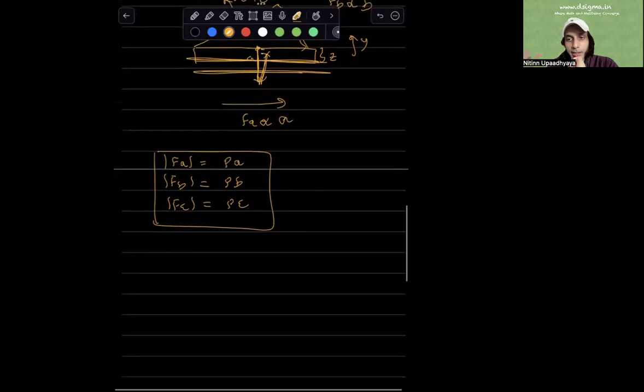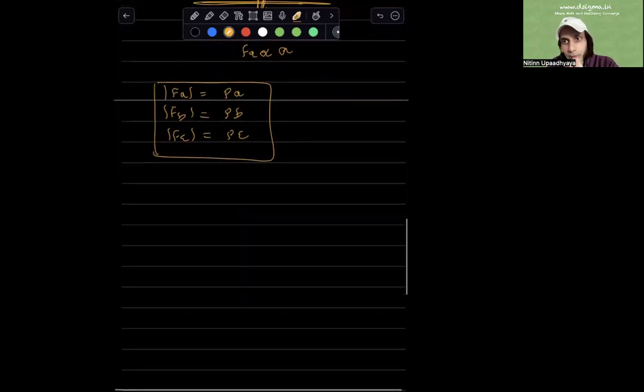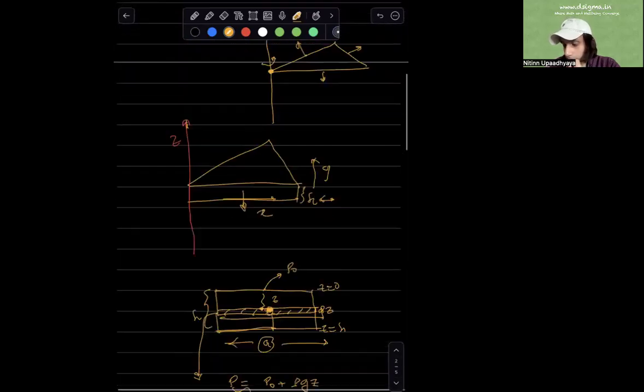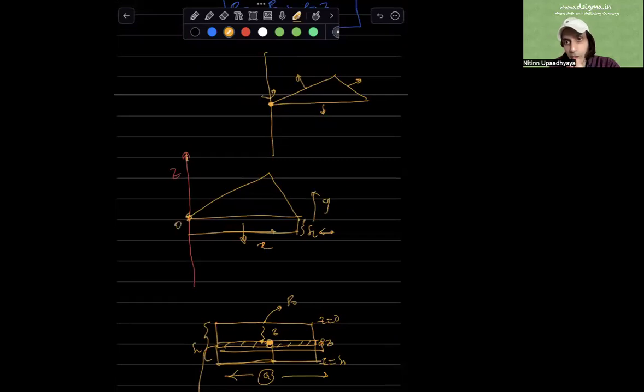And this is the interesting feature which we wanted to bring out, and that's the reason why the pressure distribution along the height of the sandwich box is important, because that gives us an expression for a force which is proportional to the length of the sides of the triangle, right? Now what we need to do is write down these forces in their vectorial notation, and from there calculate the net torque being exerted around the axis of rotation, or around this pivot point O.